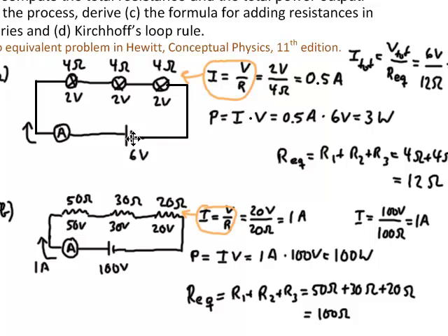And so as we go up here 6 volts inside the battery, then we have voltage drops of 2 volts, 2 volts, 2 volts, which of course add up to 6 volts. Or if we go around once, it would be 6 volts up, and then 2 down, 2 down, 2 down, which returns to the 0 over here. Same thing here, 100 volts of course equals 50 plus 30 plus 20. Or inside the battery we go up 100 volts, and then we subtract 50, 30, 20, and come back to 0 volts on the minus or ground side of the battery.